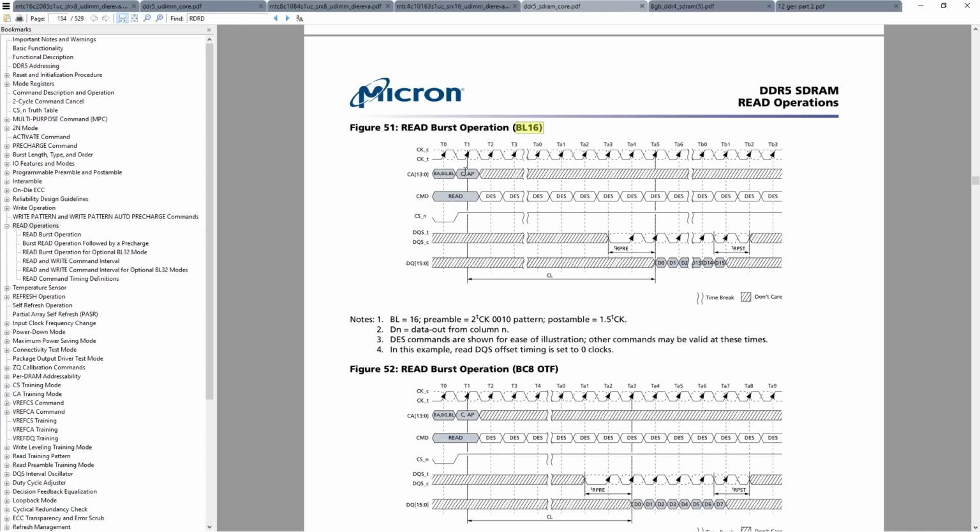Not really, but for the longest time, the mainstream Intel memory controller was actually 128 bits wide, single channel. It didn't behave like a proper dual channel memory controller, and one of the benefits was that it had really good latency, at the cost of being kind of terrible when you had a lot of random data access that you wanted to do.